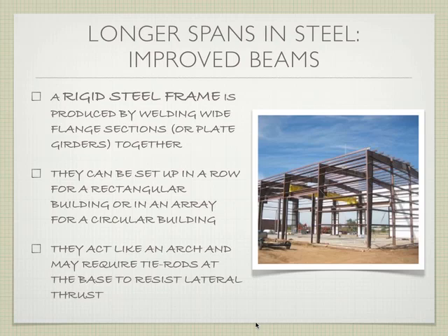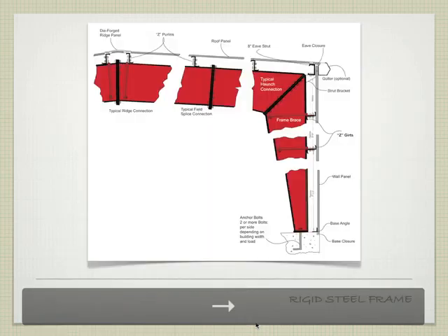So it's basically like a curved beam, so to speak, right? And it's going to allow all of that long span that comes down into the side. Okay? This, however, if we put too much pressure here, it can cause the whole thing to want to kick out from either side. So it does have outward thrust that a lot of times you have to handle in the foundation itself, right? So this is what I'm saying about they need tie rods, right, or buttresses at the base to make sure that it resists that lateral loading, right?